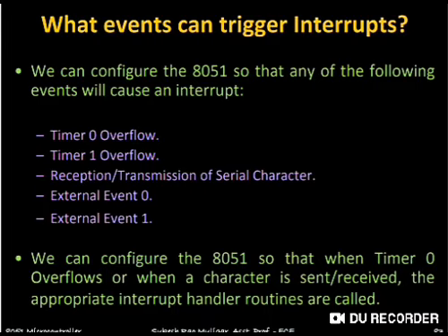So whenever the serial buffer, that is the SBUF register, is loaded with the character byte, serial communication begins. So how do you know that the serial communication is completed? That can be observed using the TI flag bit. So that TI flag bit can be used to monitor the interrupt. Similarly, receive also. External event 0 and 1 can also be used here. So these are all the event triggers we can use in 8051.